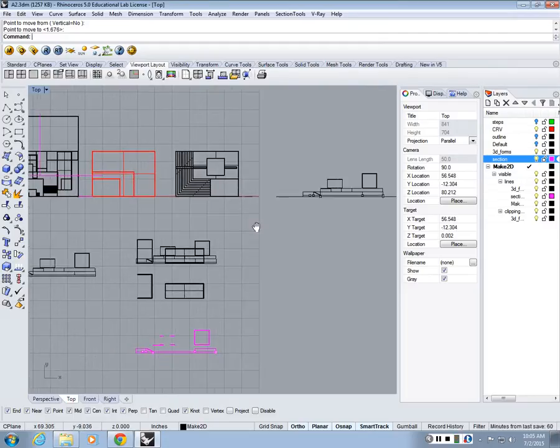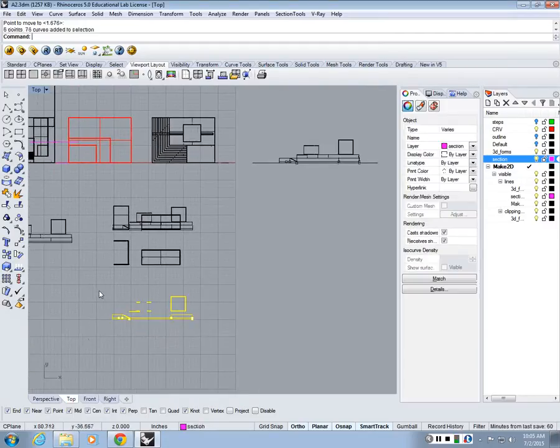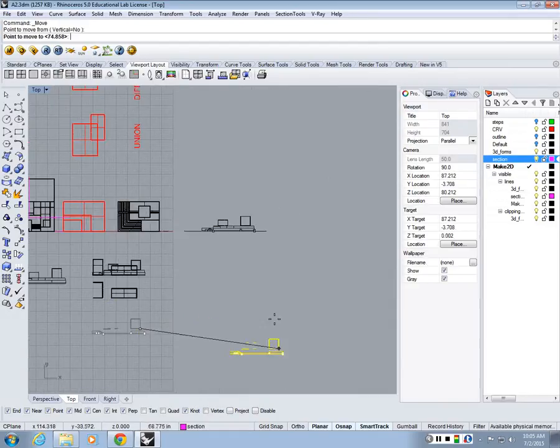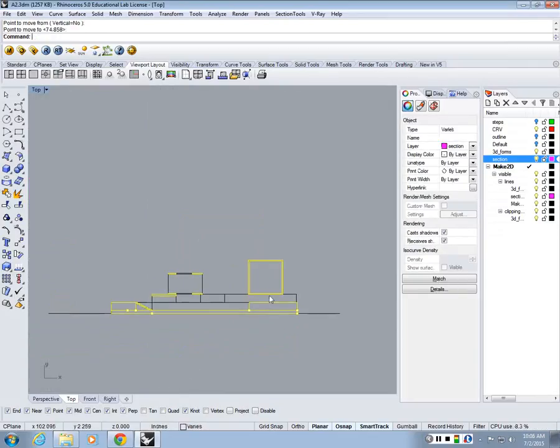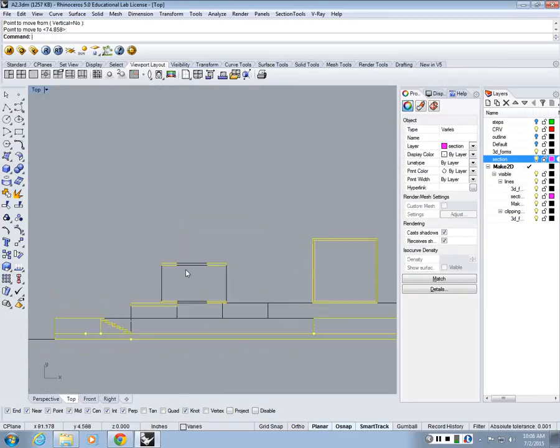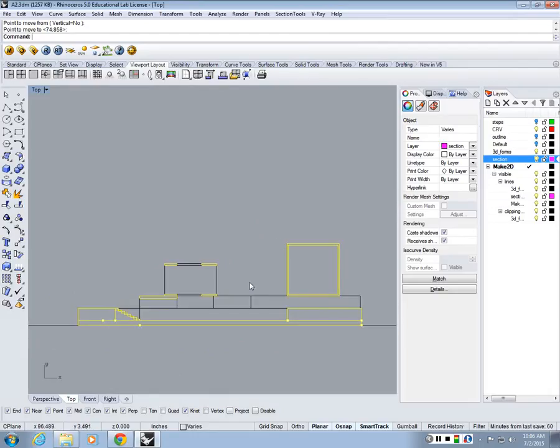So this will be kind of an outline or template for me to use for drafting my section. But what I also want is to overlap it with the section lines so that I can add a Poché to these elements. So if I were to bring this on top of the actual section, the lines that you're seeing as highlighted will be shaded. They will be Poché because they're cut, right? But the other remaining black lines will be lighter because they are not cut elements. They're seen in elevation.